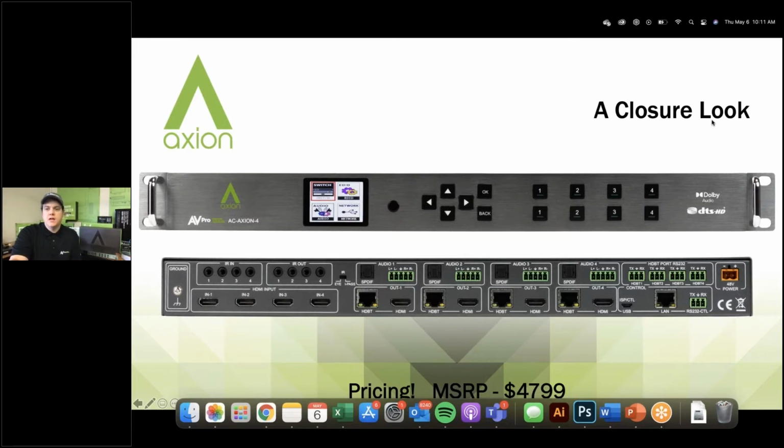A couple more questions. I'm going to just go in here. HDMI 2.1, and will it support higher than 18 gigabits per second? No, this is an 18 gigabit per second matrix switcher. It may have a 24 gigabit per second backplane on it, but that would be something in the future that we would have to update. Right now, we do not have any HDMI 2.1 matrix switchers. Our first one is going to be our 8x2, and I guarantee you, Paul, I will make sure that you hear about that because it will be a big deal when we're switching 8K. But this is going to be able to handle all those things.